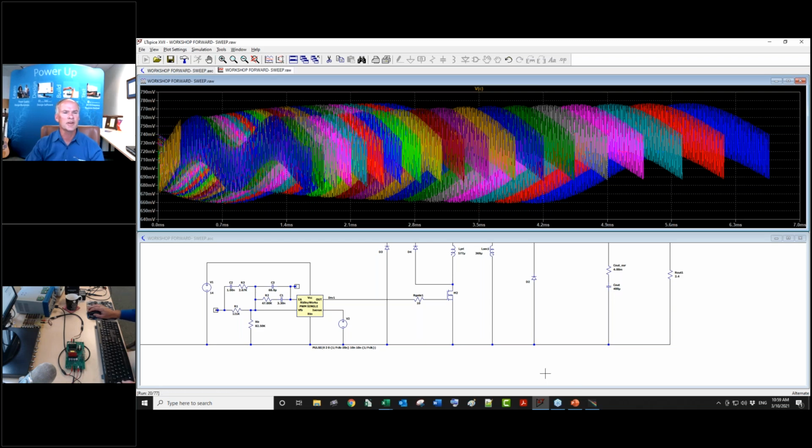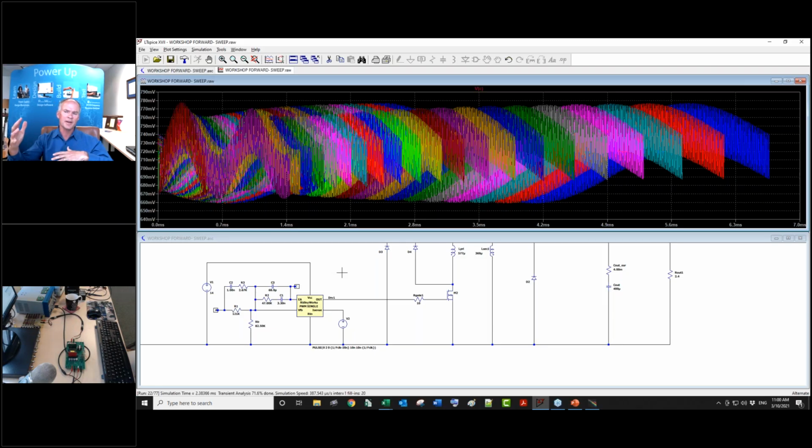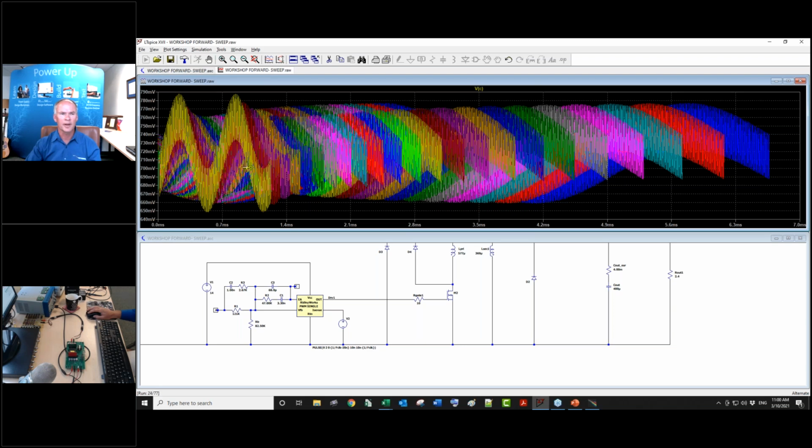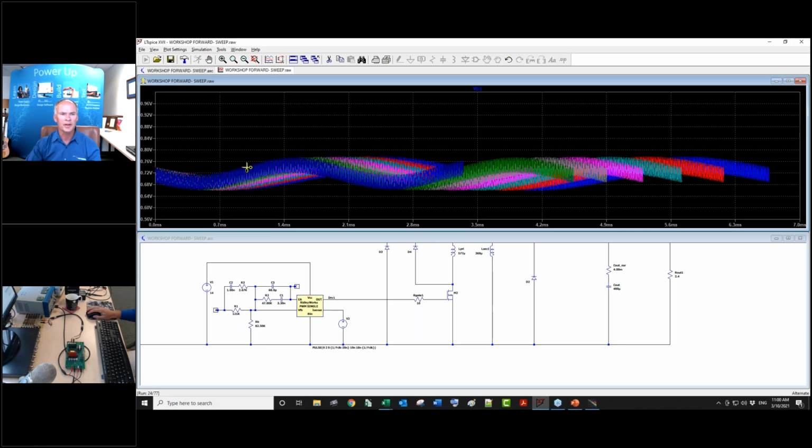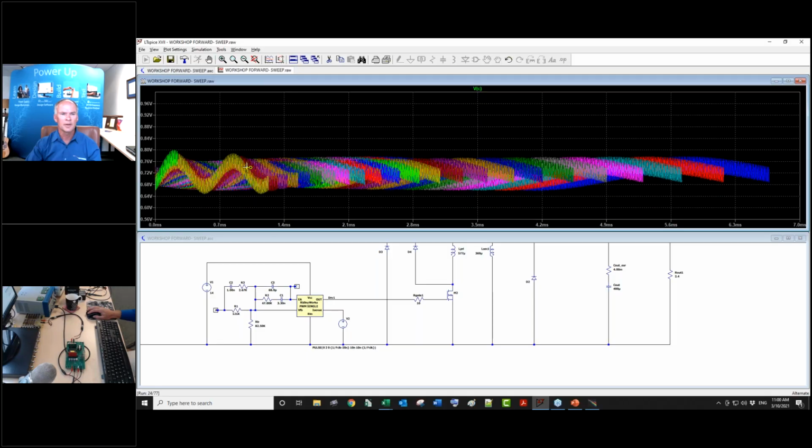Spice likes to take its sweet time. But again, now you can see that signal size there started to grow. It went through a little bump, then it came down here, and now it's started to approach the crossover signal. So the two signals are going to shift. The A signal is going to get bigger, then it gets multiplied by the compensator, and we can see that there's more and more modulation appearing on the output of the compensator here. Oh, there it is, taking a big jump there. And then just a couple more. I had to rescale there because it's getting bigger. Okay, 0.8 volts on there.